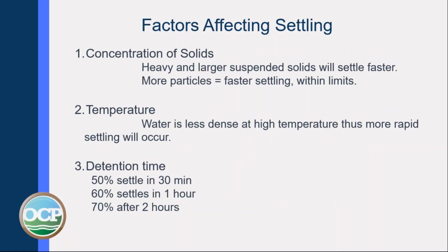Some of the factors that affect settling in your clarifier: the concentration of your solids. The heavier and larger suspended solids will settle faster. The more particles you have in there usually equals faster settling. Temperature. Water is less dense at high temperature, thus more rapid settling occurs. As the temperature drops and the water gets denser, it will slow down the settling of these particles.